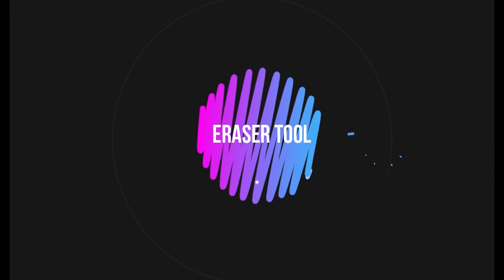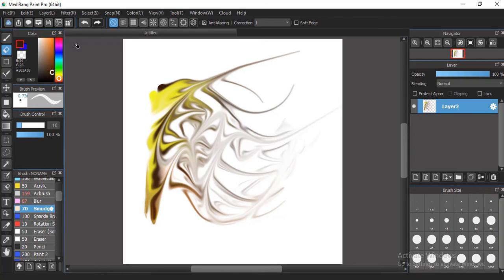We can use the eraser tool in 2 different ways. First, we can use it with 100% opacity to remove the lines completely. You can see that, and if we lower the opacity of the eraser tool, it's not going to be removed completely. You can see the color is lighter.